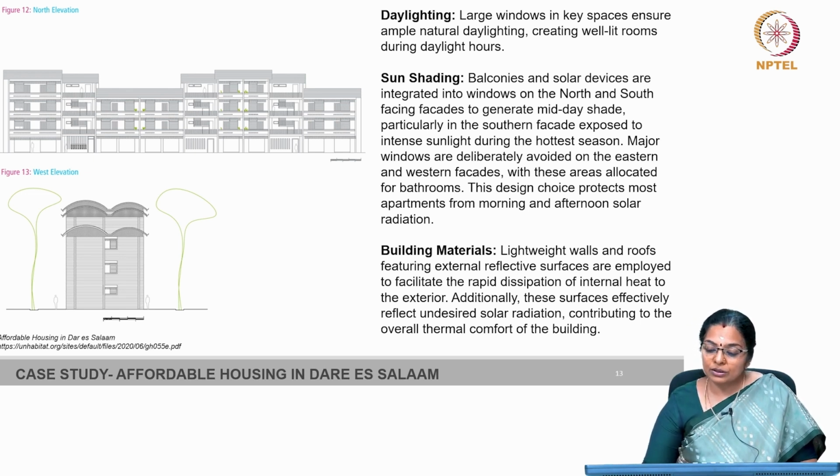So, they have used sunshades and other shading devices strategically placed along the openings, balconies, windows, and this design choice protects most apartments from morning and afternoon solar radiation.